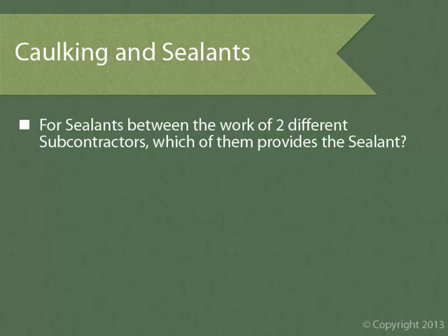In other words, if we have a curtain wall with purple sealant, meaning a metal panel system with orange sealant, what color should the sealant be at the intersection where these two systems meet? In a perfect world, this direction would be found in the contract documents, but the reality is that we rarely find this in the drawings and usually need to ask the architect for a confirmation. Obviously, whichever system the sealant is to match will determine which sub provides it.